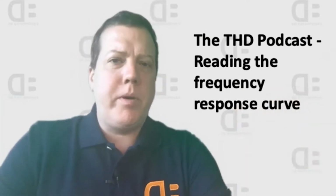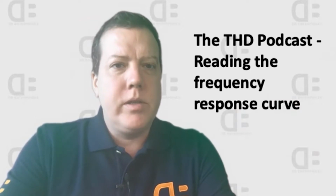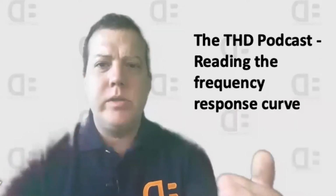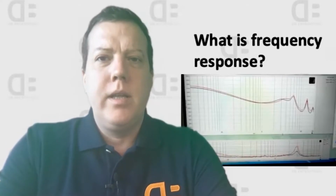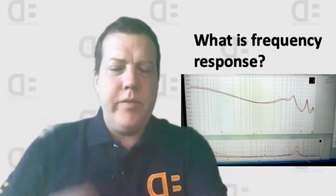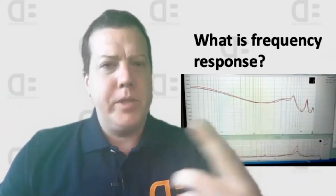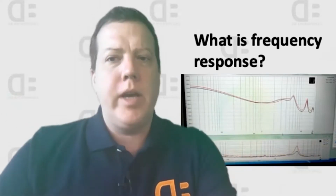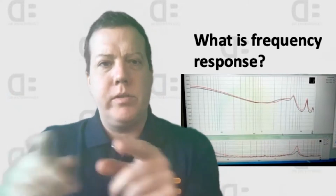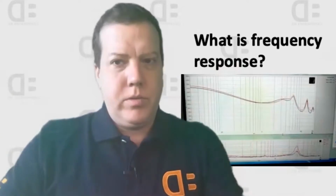Another episode of THD Podcast. Today, Simon's with us in Japan, and we're going to talk about reading the frequency response curve. This is a fundamental tool that's used by everybody building audio devices. So we want to know, what is a frequency response? Basically, it is an input-output measurement function. You're taking amplitude and phase, and you're getting a measurement of the output in terms of a frequency response. So you can see it across the whole spectrum of what's audible, even beyond what's audible by human ears for some really fanatics out there.